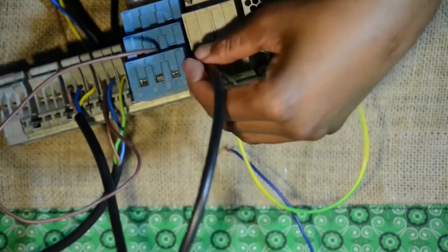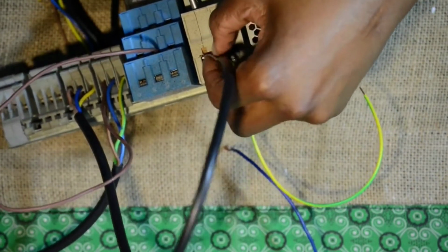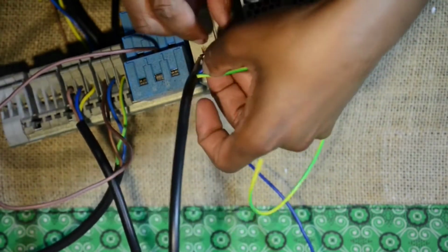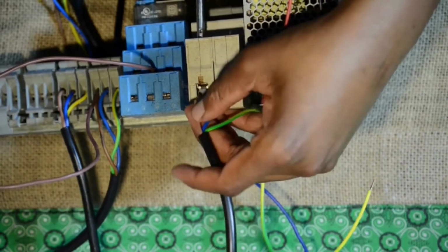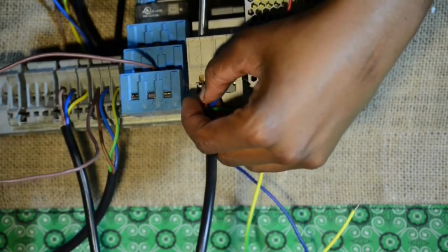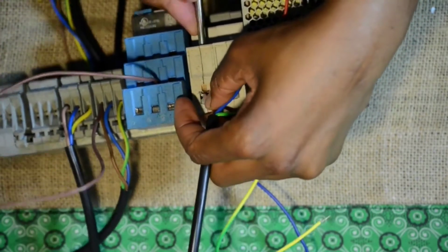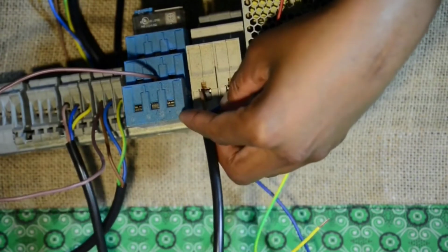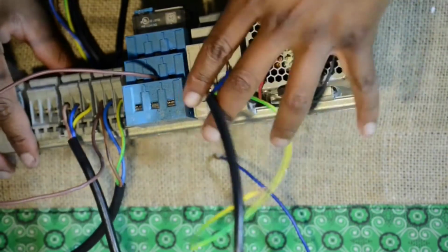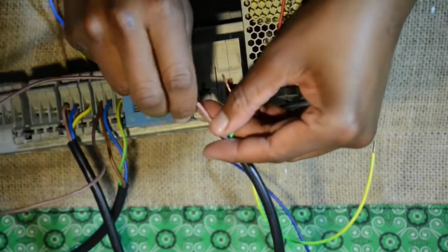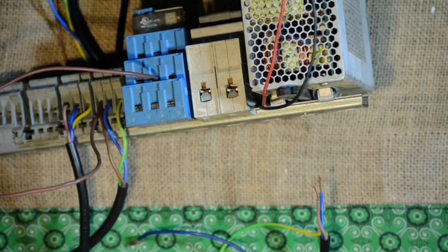So what I'm doing, by running it through a circuit breaker, is that if there's a fault in the load that has been detected by the mains, it will also be detected by this secondary source, which is the inverter. So it will also trip. So if there's a fault in our load, both systems will be off, right? So if you don't put the circuit breaker in, it's going to be tragic if something goes wrong. So make sure that you have a circuit breaker there that works perfectly.